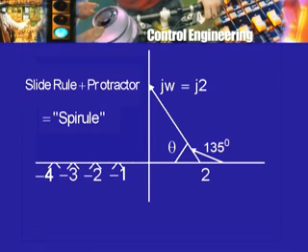So tan theta is 1, and fortunately I don't have to use a pocket calculator to find the angle whose tangent is 1. The angle is 45 degrees if you want an acute angle. So this theta is 45 degrees. So what is this angle? The angle subtended at the point by the zero, measured in the anticlockwise or counterclockwise direction from the positive real axis. Here is the positive real axis, here is this vector pointing towards the J2 point, and so I have to measure this angle in the counterclockwise direction. So what will this angle be? It will be 180 degrees minus 45 degrees, or in other words it will be 135 degrees.